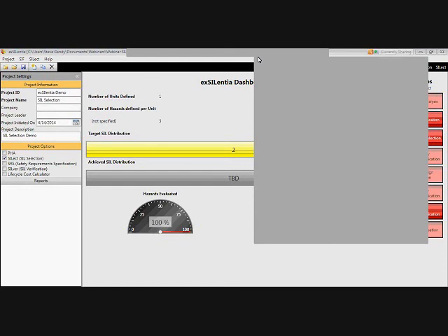And of course, testing is very important. Proof testing is something that is also taken into consideration when doing the SIL calculations using Excellencia. So that's just a word of warning. Be careful. Make sure when you do your SIL selection that you do err on the conservative side. Obviously you don't want to over-design because it becomes too expensive, but you need to make sure that if you do decide, okay, I am going to go with a SIL 1 with a risk reduction factor of 20, okay, fine, but just be aware that that's a conscious decision to do that.